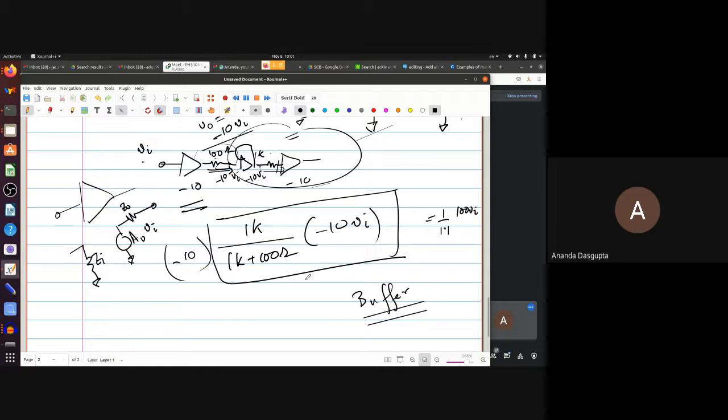But apart from that, notice that once you've constructed the op-amp, the basic idea is that the op-amp has a huge gain, a very low output impedance and a very high input impedance. That's how it's constructed. Now, when you couple that with negative feedback, you can get very precise results out of it.